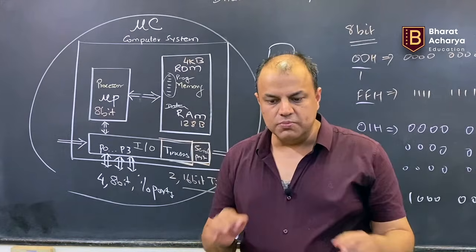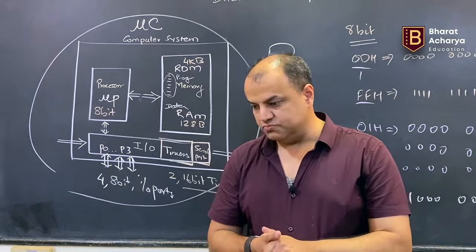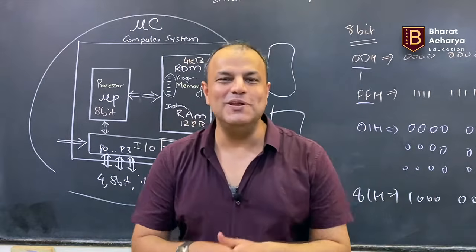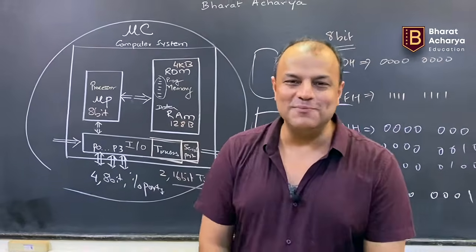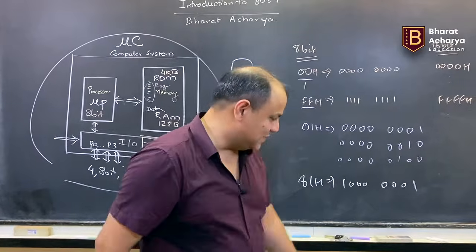Serial communication is slow because it's bit by bit. To send 8 bits will require 8 cycles. So yeah, it's slow. So should we study it? Yes. 90% of the communication it will do will be serial communication. What's the advantage of serial communication? Cheap. You need one wire to do it.